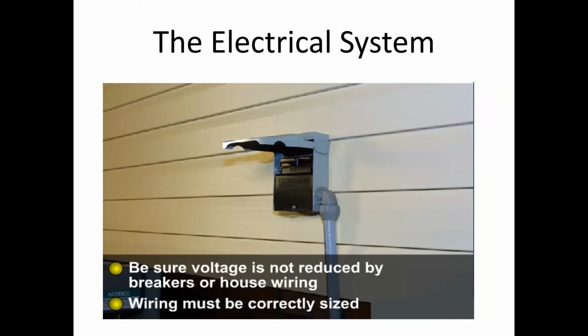Again, I mentioned this earlier, make sure that you don't have a voltage drop or your voltage isn't reduced by any wiring connection, right? A loose wire, a bad wire nut, a terminal that's not properly crimped, any of that stuff can cause a voltage drop, as can wire that's too small. If you've got undersized wiring, just like a bad wire nut or a bad connection, that's going to cause higher current, or a greater amp draw.